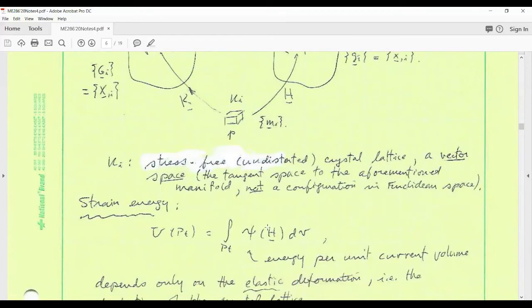If you remember in the first lecture, we introduced the notion of an energy, which for a linear elastic response with a Young's modulus and small elastic strain would be something like one half the modulus times the square of the elastic strain. And the elastic strain was the natural log of the elastic stretch.